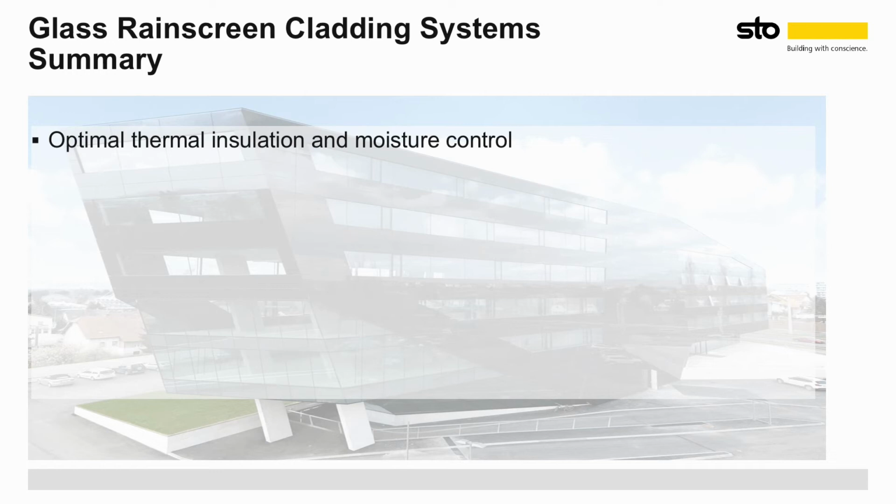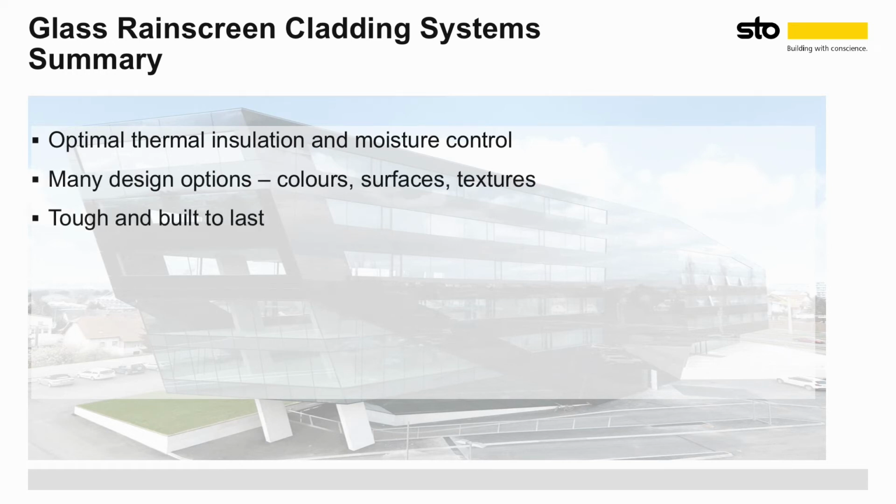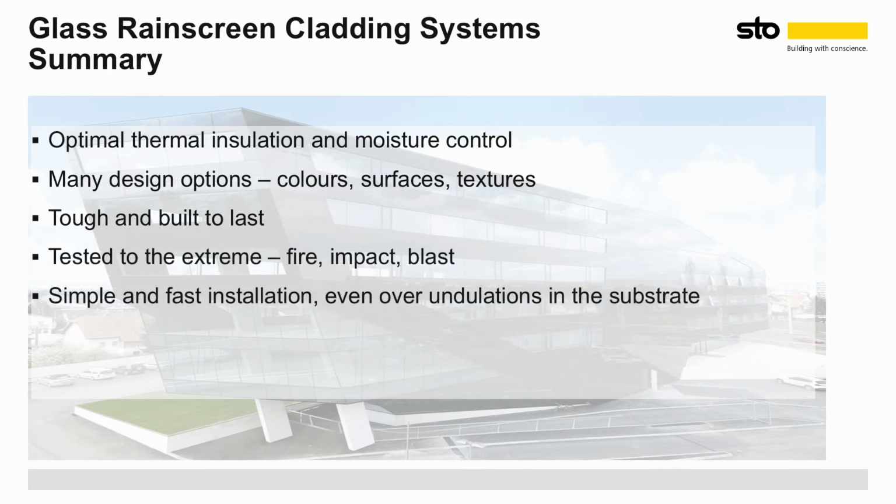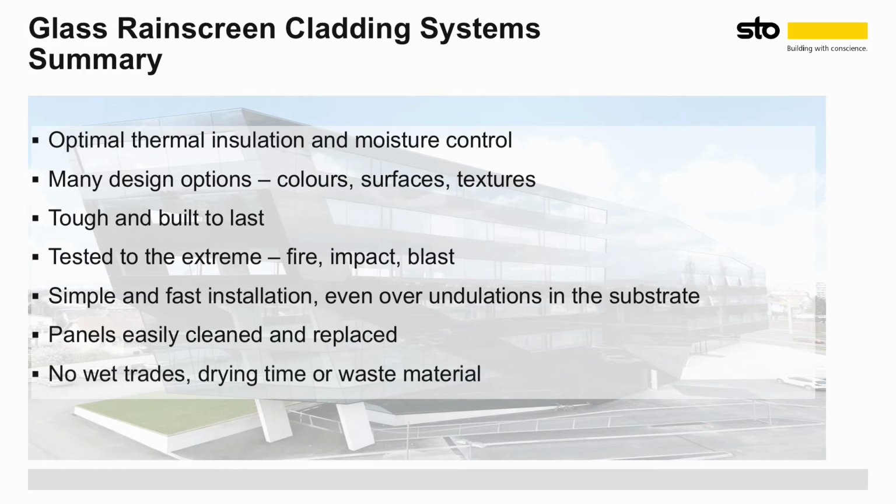They provide optimal thermal insulation and moisture control and are tested to the extreme in relation to fire, impact and blasts. No wet trades are required during installation, so there's no need to consider drying time, weather conditions or waste materials on site. The systems are generally bespoke to the project and there are many design options available: colours, surfaces, textures.